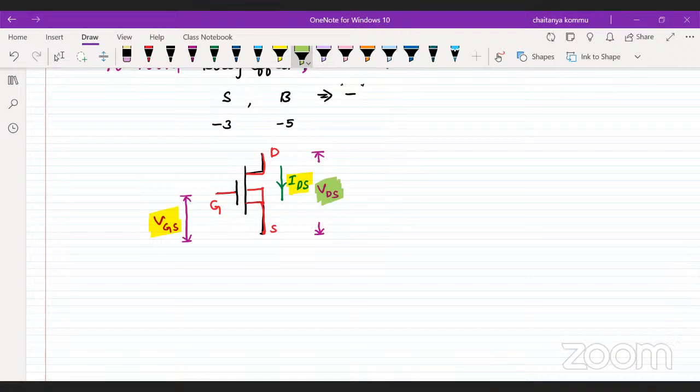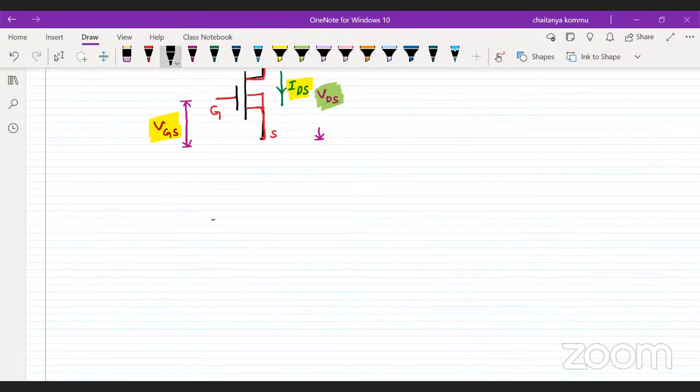What's my point here is that in this analysis I want to make sure that the transistor must be on. For that, I'm going to use VGS. And if you want to transfer the electrons from source to drain, that means I want to evaluate the IDS value based on VDS, right? For example, if this is my transistor, consider that body, bulk and substrate are connected to the same potential.